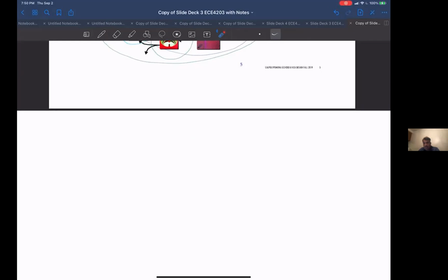They can deposit donors or acceptors, N or P type dopants, into the silicon at different energies and different concentrations, which means you can get higher values of N or higher values of P, and you can get them at different depths. Higher energy puts it at a deeper depth in silicon, and lower energy puts it closer to the surface. The different concentration gives you either an N plus, which is a lot of N, or N minus, which is not so much. So you have those tools. And then you can deposit oxide and deposit metals and pattern.